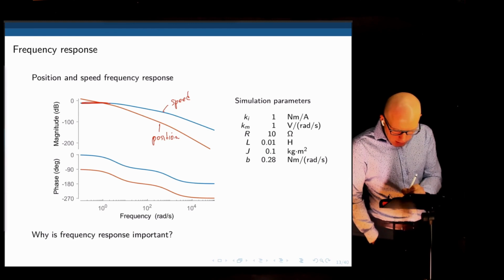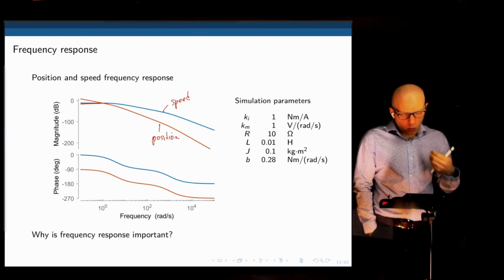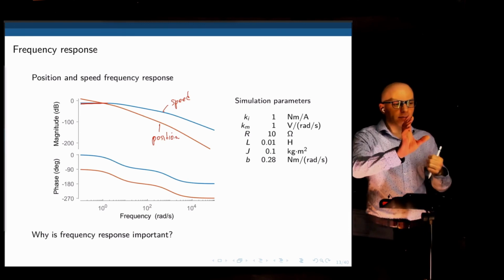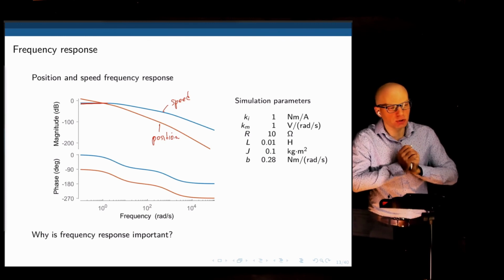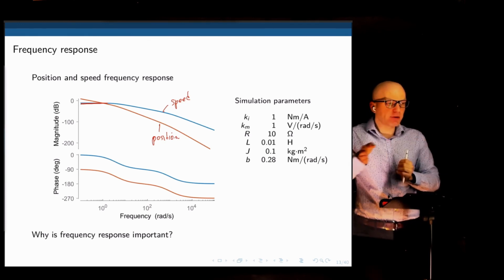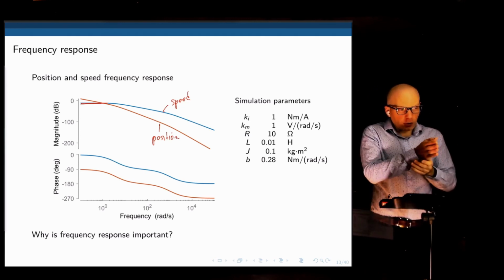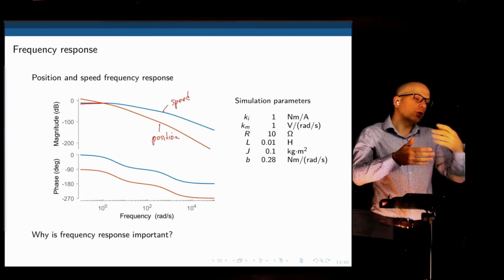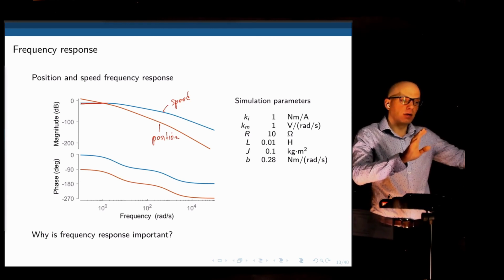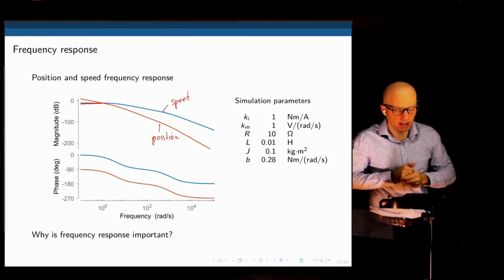What does this mean? Well, it means that if we start giving the motor 1 second to rotate, and we look at the maximum speed, then you divide the maximum speed by the input voltage. We take 20 log of that and put it here. It's a flat curve. Does that make sense? Well, it makes perfect sense, because if we lower the frequency, we are giving more and more time for the motor to spin in one direction, reach a steady state, and then reverse direction and go to the other direction and reach steady state again.